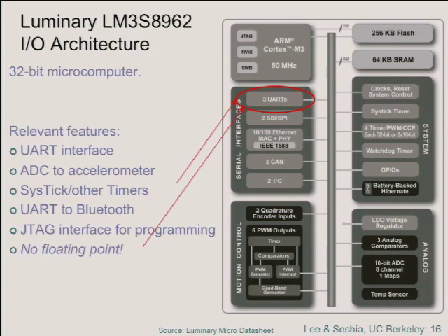The first one was that the connectors and the wires are more expensive and bulkier and harder to work with. The second one was that you can't run them at as high a speed because there's intrinsically more capacitance in these connections, partly as a consequence of there being more wires bundled together. And the third one is synchronization problems.